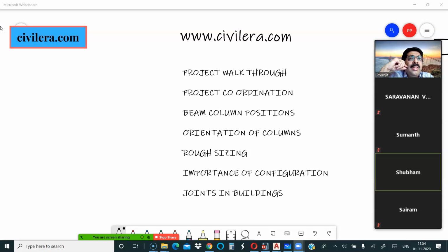In 2 floors, even in 1 floor, you have to tie the columns wherever possible. Only if it is a cutout and if it's a double height column you will have an issue.